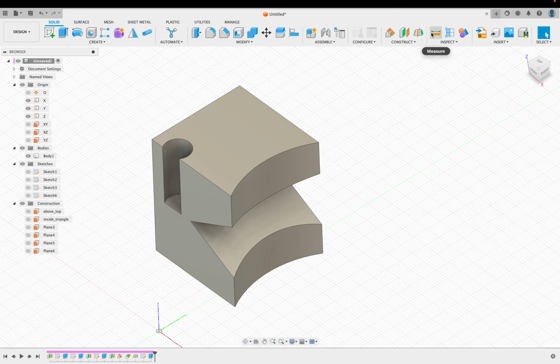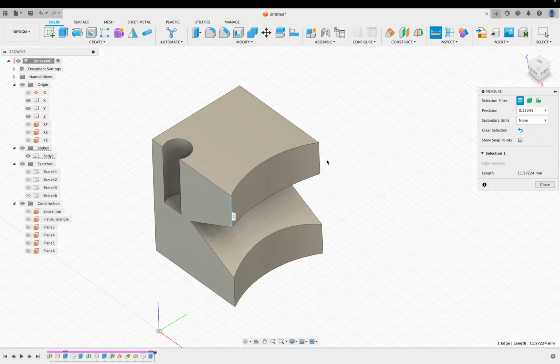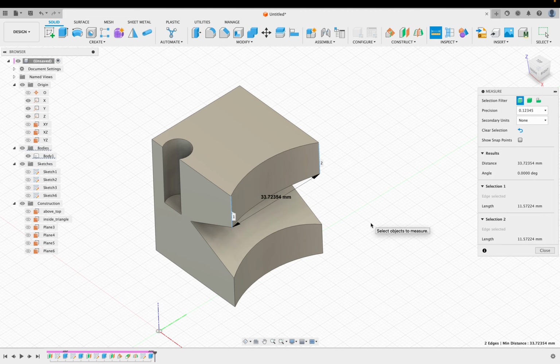If you ask me, let's see what the measurement gives. Okay. Now the measurement is giving a distance. It's not giving an angle. So Fusion actually thinks that these two lines have a distance and not an angle, which means they're parallel. But at some precision that is further away from this dot, maybe the 8 or the 10 point. Let's see if we can see this. Yeah, see?